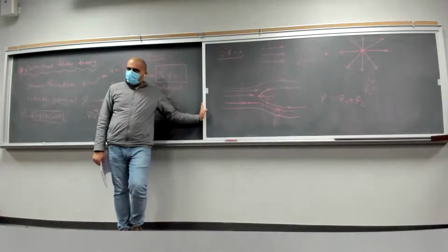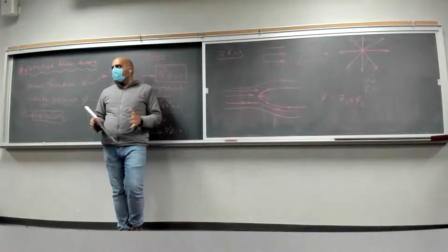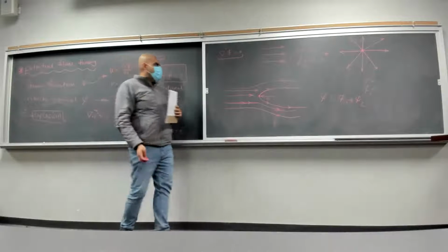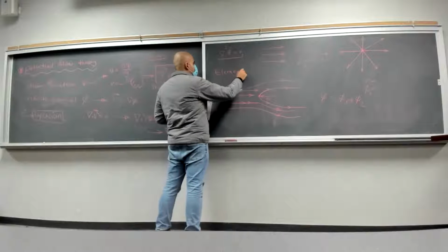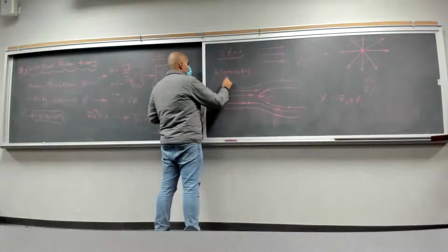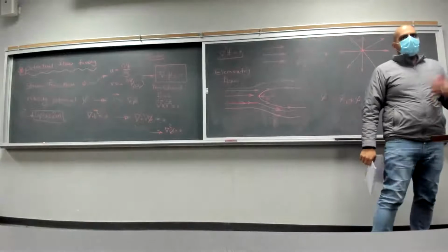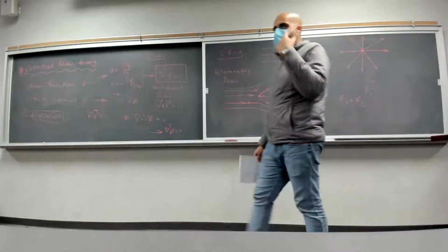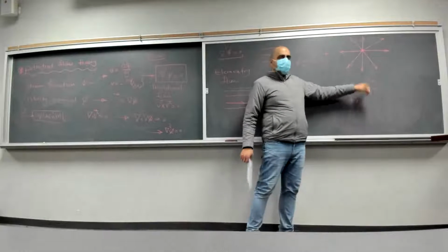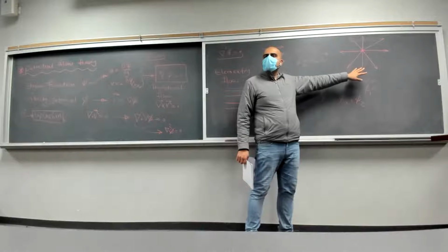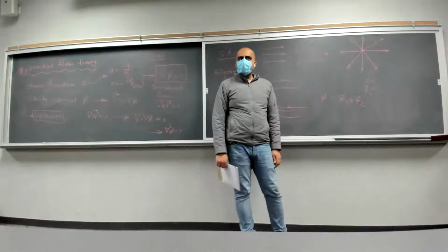Okay. So essentially, as long as we can come up with a couple of elementary flows, what we call elementary flows, like these two, we will be able to build more complex flows. The only thing we need is to find the velocity potential and the stream function for those elementary flows. Then we can create more complex flows, whatever you need, essentially.